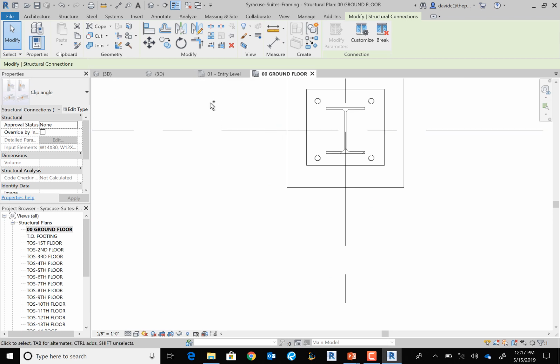So going back into my ground floor, did you guys have any questions on those connections before I move on? I'm going to go into placing loads and things like that now. Yes, sir. When you propagate the connections, it's making adjustments based on size. So is there any type of connection that it finds that it's going to create, adjusting for the size? Yes, sir, exactly. It's going to adjust those plate depths or the flanges and everything, but what it's going to do is associate the same number of bolts, or try to.